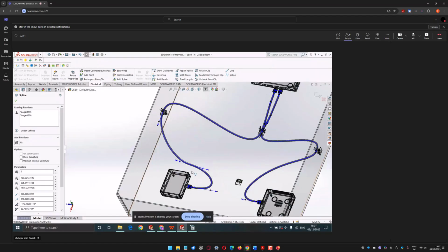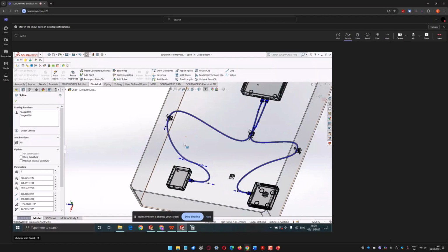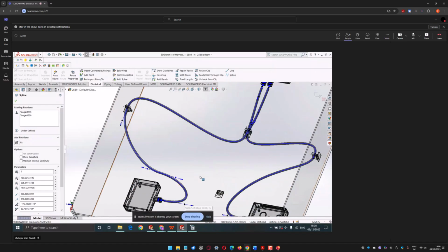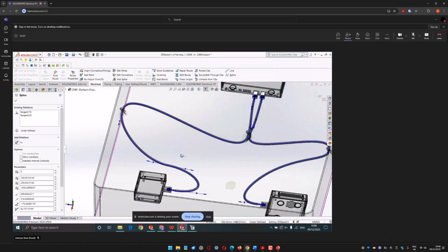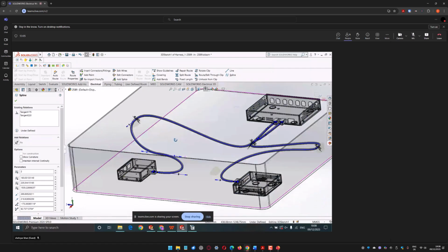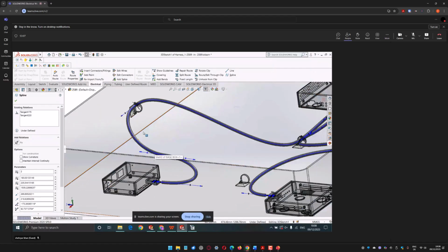So this is the correct bend radius, but again, we have to calculate our bend radiuses and choose our correct or exact bend radius which we have chosen. In this case, there is no error for the bend radius, which means that this cable can twist in these directions, and it's manufacturable, and it can definitely go through this route.